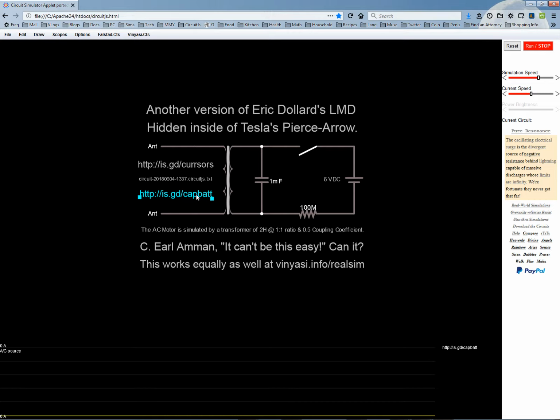Anyway, what am I getting to? So I made this 2 Henrys because 1.7 is about what my car is. It's not going to be the same for all EVs. My car is massive. It's over 3,000 pounds, in fact around 3,400 pounds. The Pierce Arrow was over 4,000 pounds. So you're going to need a lot of induction, in all likelihood, in the motor running the car. So I estimated somewhere just under 2 Henrys, and just rounded off for this simulation, made it 2 Henrys.